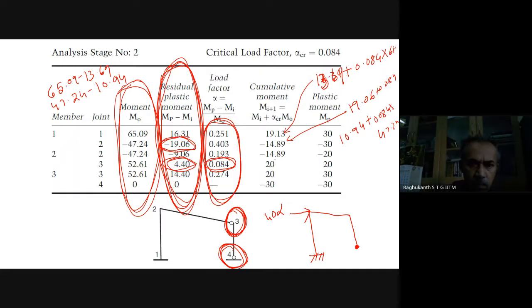So now after doing this one, this place automatically becomes 20, and the plastic movement automatically happens in the column. So the third hinge gets formed itself. Okay, so this is our stage 2. Although a hinge has formed, this portal frame can still take load, because only 2 hinges are there, and it's still a fixed support, so it can still take the load. There are still some joints which are not yet plastified.